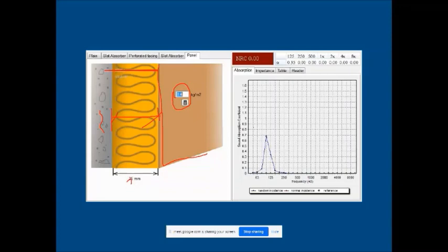To see the performance of this particular assemblage of material, we have plywood, concrete wall, and in between wall and plywood we have 25 mm thick glass wool, right? Now this graph shows how it is performing. This is frequency of sound, we have 63, 125 Hz up to 6000 Hz, and this is sound absorption coefficient. So you can see for this particular frequency range, maybe around 70 or 75 to 120, this is kind of a good absorber. We are getting up to 0.7 and a very sharp edge.